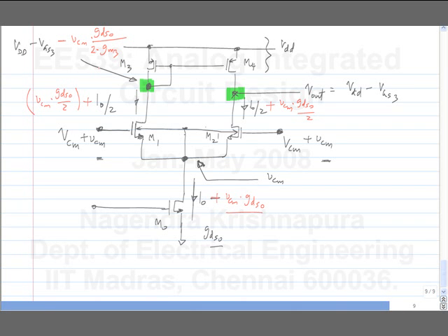So I have this transistor M3 here. And I had a certain current flowing I0, and it changed to I0 plus VCM GDS0 by 2. So whatever voltage was here, quiescent voltage, it will change by VQ minus the current increment divided by GM3. Okay. So the red parts here are the increments and the black ones are quiescent quantities.